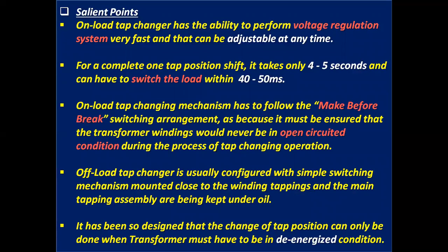Salient points. On-load tap changer has the ability to perform voltage regulation very fast, and that can be adjustable at any time. For a complete one tap position shift, it takes only 4 to 5 seconds and can switch the load within 40 to 50 milliseconds.